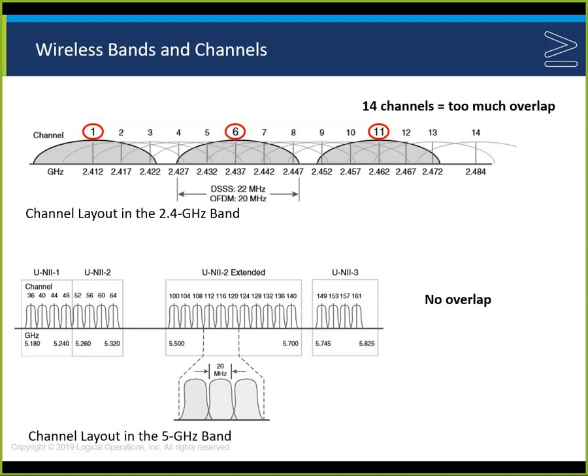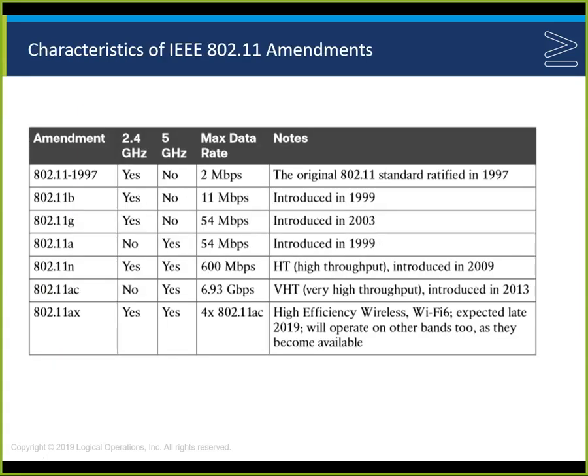What it would do, now 40, these are 20 meg. What it would do would bond these channels together, so we have a great big bandwidth in here. The bigger the bandwidth, the more data we can put on these things, more data that goes onto it. So it would bond into the 40 megahertz channel to allow us to have the bigger configuration that we wanted to do. And get back to the one that we were on.